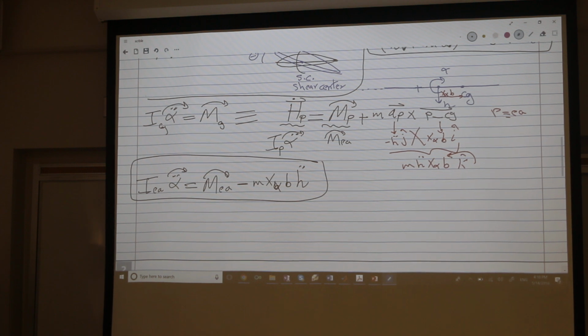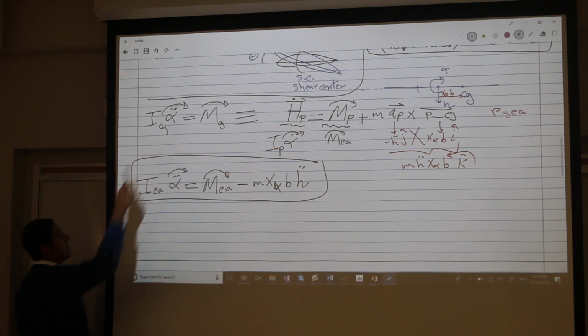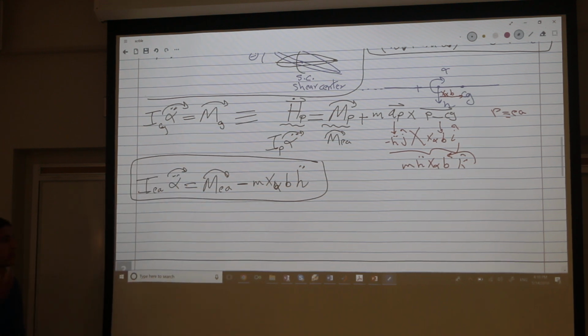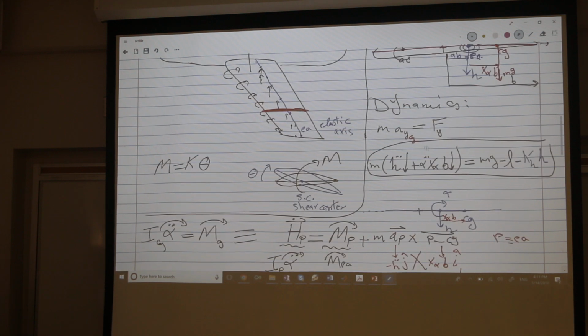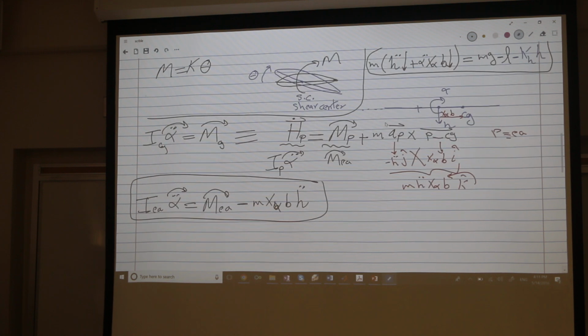But it's one of the things that are a little bit tricky, because this equation is very famous, and we think that it's applicable at any point we're rotating. Yeah, no, the CG is a very special point indeed. Also, this equation is not applicable at any point. You cannot say mass times acceleration at any point equals force at that point. It has to be the center of gravity, otherwise it's not correct. The center of gravity is indeed special because of that for a rigid body.